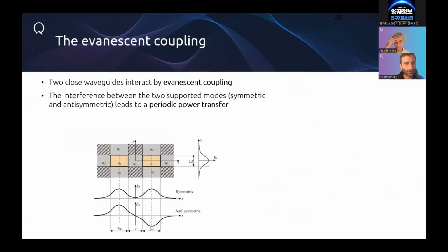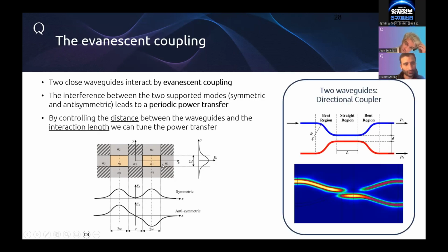I will show you how to make a beam splitter using this. We don't have mirrors in photonic integrated circuits. We only have waveguides. Here you see the cross section of two different waveguides, and the point is that if you do your mode calculation of how the light is traveling there, you will always have a bit of light outside of the core, defined by the refractive index N1, and you will always leak slightly some light into the neighboring waveguides.